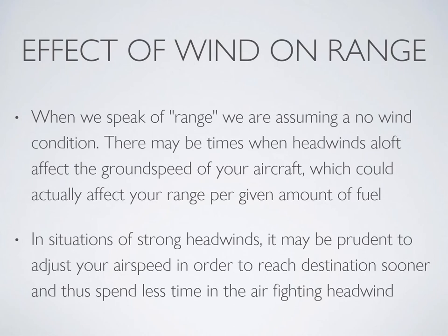There may be times when headwinds aloft will affect the ground speed of your aircraft, and that could actually affect the range that you have per given amount of fuel. In situations with a strong headwind, for example, it might be prudent to adjust your airspeed to reach your destination sooner and therefore spend less time in the air fighting that headwind.